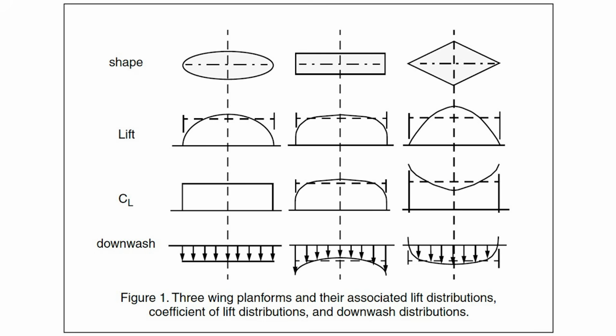Tapering wings biases the lift and drag towards the wing root, minimizes the bending moments, and allows for a lighter wing spar. Structurally, this keeps the lift-generated bending moment relatively constant across the span, which decreases the structural requirements of an equivalent rectangular wing at the cost of slightly lower lift.